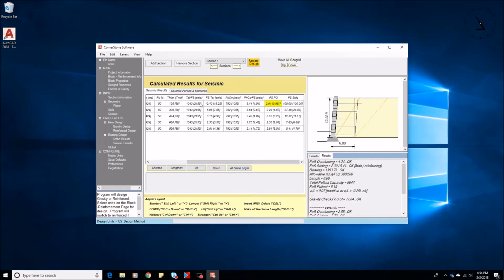As we come across the table, you can see our Tmax value and the Tmax MD, the seismic component, are quite a bit different, and the factors of safety with seismic, without seismic, the static peak connection with seismic.